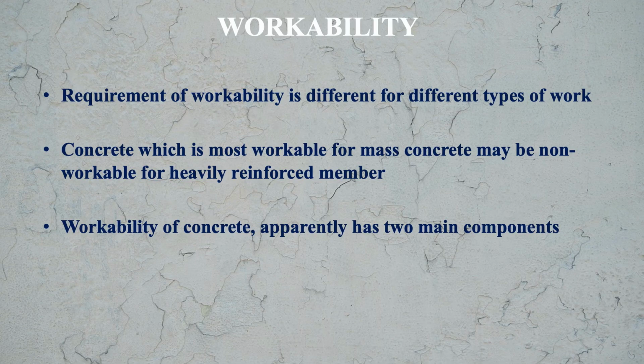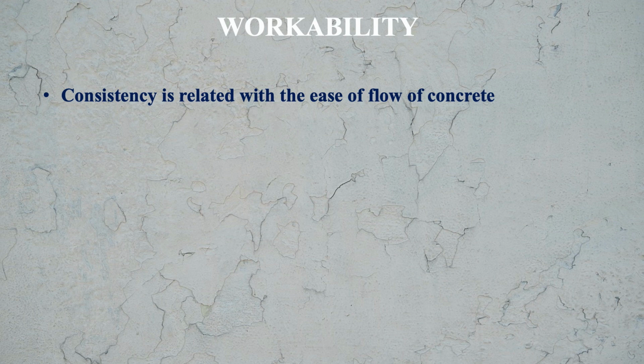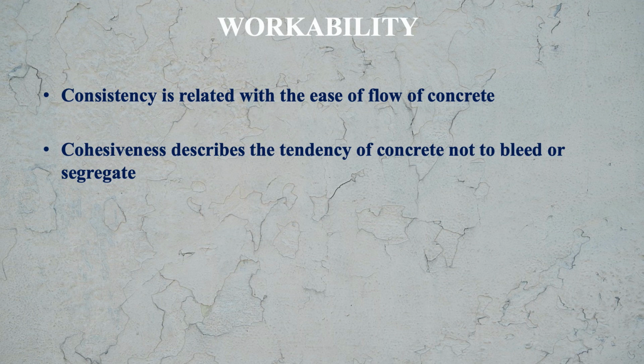Workability of concrete apparently has two main components. First is consistency, second is cohesiveness. So these are the two important components of workability. Consistency is related to the ease of flow of concrete, meaning how easily concrete can flow, and cohesiveness describes the tendency of concrete not to bleed or segregate. This means the mix is cohesive, the ingredients are not separating. All ingredients are remaining at one place, properly distributed.